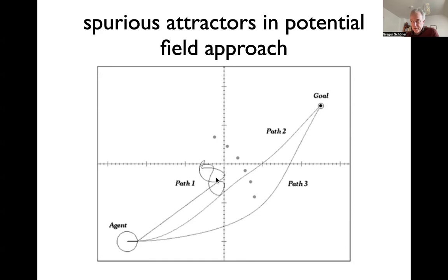Typically, the obstacle is important only when the obstacles are in the way as you go to the target. If the obstacles are off to the side, that doesn't really matter much. So these spurious states arise exactly when the obstacle is on the way to the goal. Many potential field implementations that are being used have some special-purpose mechanism to deal with that. Some approaches do that by integrating ahead of time and finding in simulation that there is some state where you get stuck, detecting that, and when they detect it, changing parameters or adding an additional force to get you out of that state.